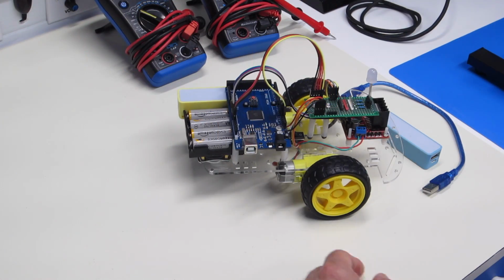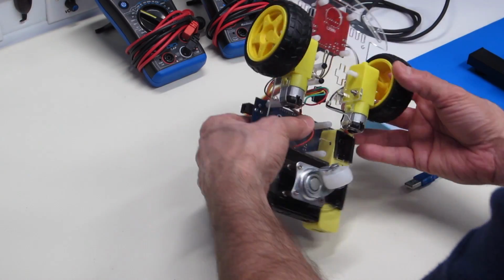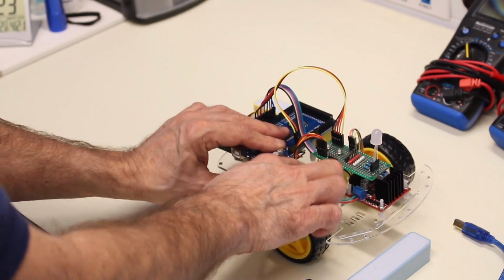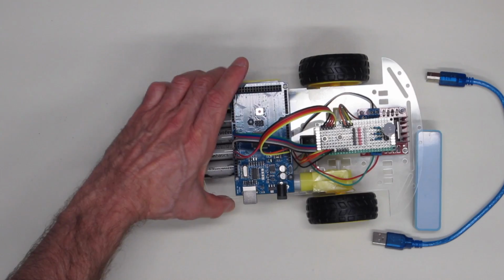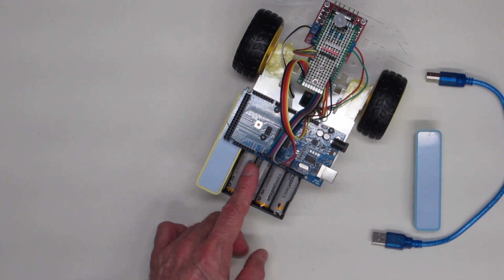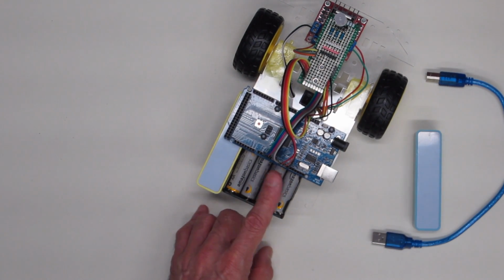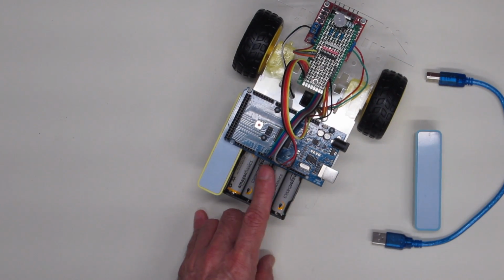our XOD robot project. So here's our little XOD robot. As you can see, it's a fairly simple design. It's on a standard robot base that you can buy pretty well anywhere. It's got two wheels and a caster on it. There's also a little power switch on here, and that's to switch the supply voltage to the motor on and off. Now, speaking of supply voltage, I've used 4 AA cells to provide 6 volts over here, and this is going to be for powering the motor, as well as for an additional servo motor that isn't on the robot at the moment. That's for a future iteration of the design.